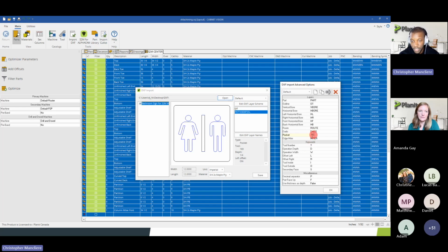So after PK, you can put a T. You don't have to. Those are mostly optional, it just depends on what you want to do. Here T means I want to use a specific tool, and you use the tool number, which is the one you type in TM. Right now I've said T and I put the tool number 103. Then the D is for depth. That's where I want to define the depth of my pocket.